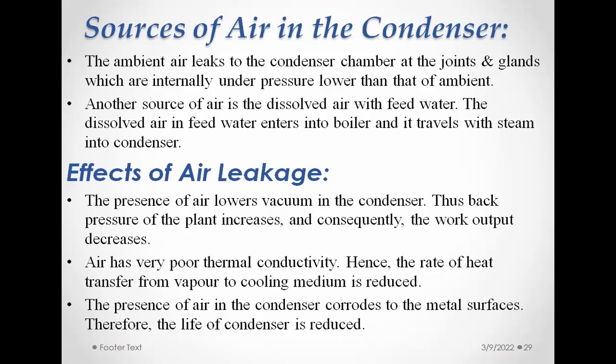Next, air has very poor thermal conductivity. Hence, the rate of heat transfer from vapor to cooling medium is reduced. So this may be another new concept for you, thermal conductivity. In short, if you take a brick or a wall, and there is some temperature here, let us say 400 Kelvin, and a temperature here of 300 Kelvin, how fast this heat will flow from this point to that point depends on its property. That is called thermal conductivity, denoted by small k.